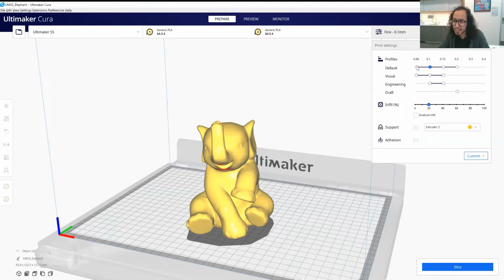It's also going to increase its print time. So that's kind of a trade-off. If you want a fast print, it's going to be lower quality. If you want a higher quality print, it's going to require thinner layers, which requires more filament and more time. And then our infill is everything that is inside and supports an adhesion.